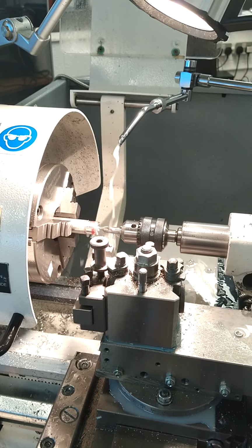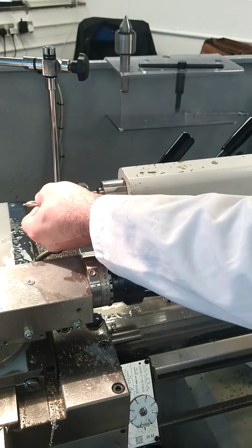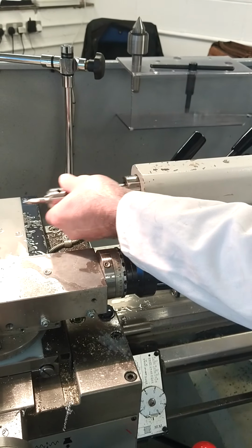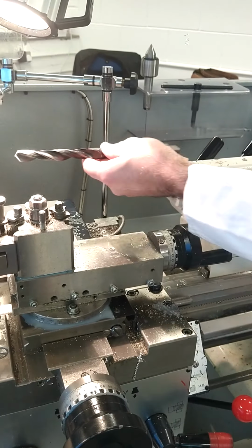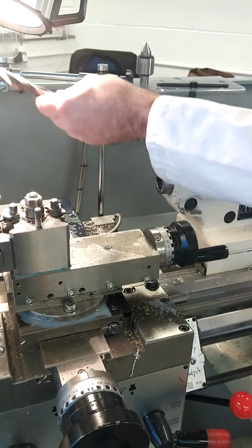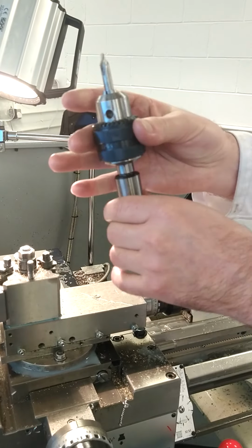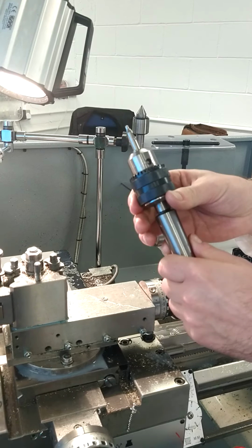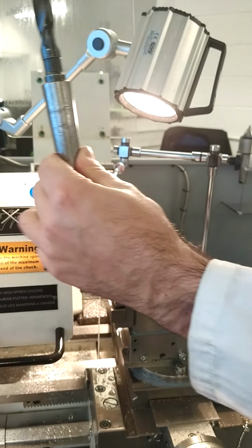Now what that allows us to do then is we can remove out this chuck, and if we like you can continue on if you wanted to drill larger holes. We can see there that for the larger drill bits they have their own what's known as a sleeve, and that's for fitting in here to the tailstock with the larger size drill bits. So drill bits up to size 13 in diameter fit into the chuck, and after that the larger drill bits 14, 15, 16, 17, 18, 20 have their own sleeve.